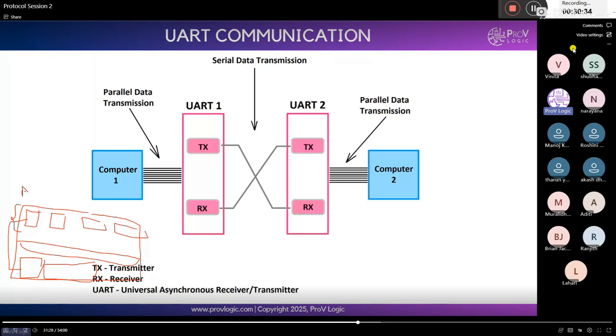Now your processor is communicating with these low power devices. The processor works at high speed, that's why we use AXI, and these low power devices work at low speed, that's why we use APB. Before you ask whether it has an interconnect or not: this whole thing is nothing but the bus. Through the bus, the processor and this block will both be connected, and every block will communicate with every other block like this. But it would be too confusing if I drew all of them, so like that it will communicate with everyone.